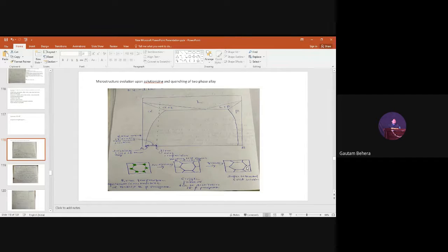If aging time will be more, precipitate size will be also more. You have to remember that. You understand? If you give a less aging time, precipitate will be very small. If you allow for an intermediate time, precipitate will be becoming bigger. But if you allow more than enough time for the aging, then you can get a bigger size precipitate, which is not actually required, which is detrimental basically. Very big size precipitates are not good.